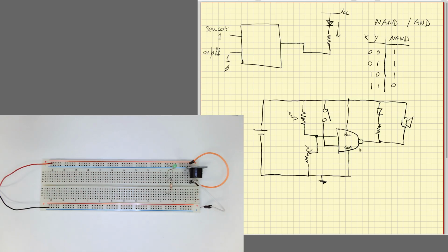So now, where do I find these NAND gates? For prototypes, there is a series of discrete components, the 7400 series, that has many integrated circuits with a few gates inside. We are going to use the 7400. This is a chip that has 4 NAND gates inside. Something like this. All this goes into a chip.